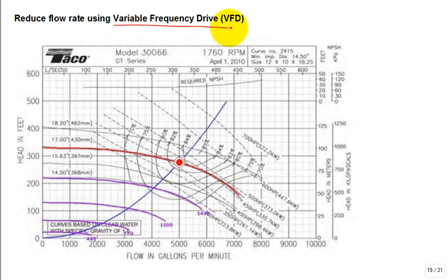So as a mechanical engineer, we really should know a little bit about it, so I throw it to you in fluid mechanics. What happens is this manufacturer even shows you what happens if I take this pump. This pump is supposed to be fed by a motor that likes to run at a synchronous speed of 1800, with a little bit of slip, that's how induction motors work. It has a 1760 RPM nominal speed. So you should hook up a 450 horsepower motor with that nominal speed to run.